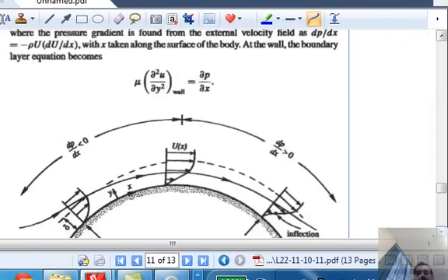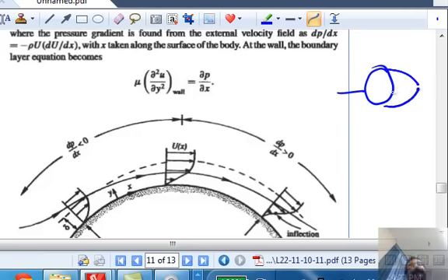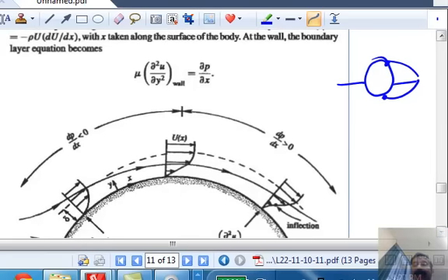And the other concept that we need to look at is separation of the boundary layers. So in a flat plate, the boundary layer does not separate. But we know, as you have done in your current assignment, if I have a sphere, when the inertial effect becomes important, the flow separates at the back. Okay, so there is a separation point. Will the boundary layer also separate? And the answer is yes, because what you will have, in fact, is a boundary layer that goes like this, and then it separates there.